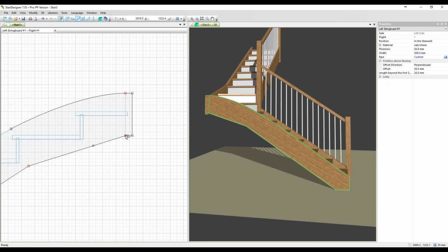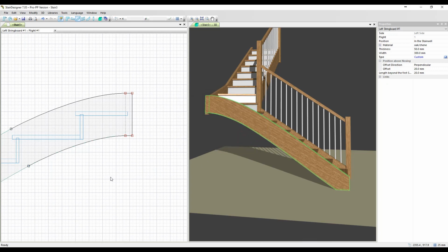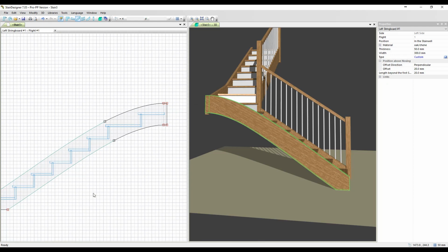So if I click here, control points appear. I can grab one of the control points. If I move it up at a certain moment, it's going to snap to the horizontal. I can see slope 0 appear, which means it's going to be actually tangent to the horizontal. This one here, I can click right, smooth vertex, smooth to the left and the right hand side, and then we've got that nice gentle smooth curve going from the bottom to the top, now drawn as splines, so it's a really nice smooth curve.